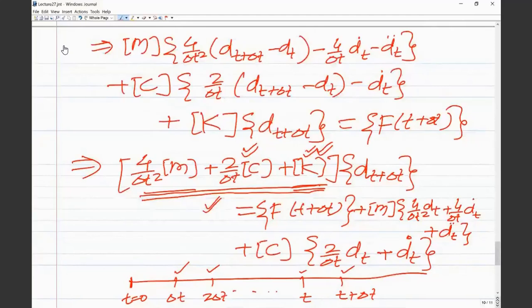Sir, for the same efficiency, which technique is more computationally efficient? As I said, typically for nonlinear problems, particularly high strain rate deformations and impact problems where the total time duration for solution is smaller, you go for the explicit technique, the central difference method.